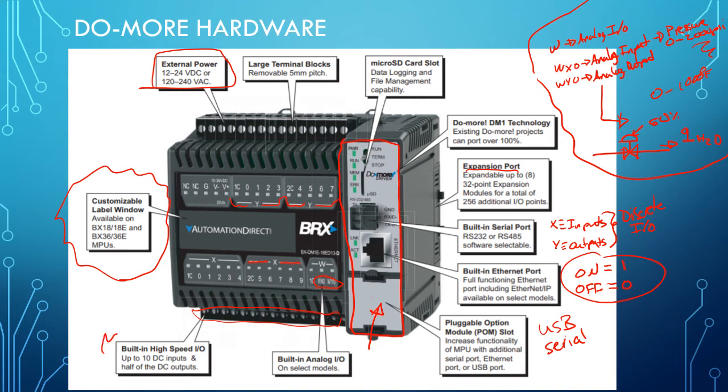You might be wondering, since it's a robotics class, about the built-in high-speed I/O. High-speed I/O are used for servo motors with encoders. Since encoders throw many pulses per minute, we could discuss scan time. Scan times on a high-speed I/O are a lot faster, and they get scanned a lot faster than regular I/O. Instead of being in the millisecond range, it might be in the microsecond range.